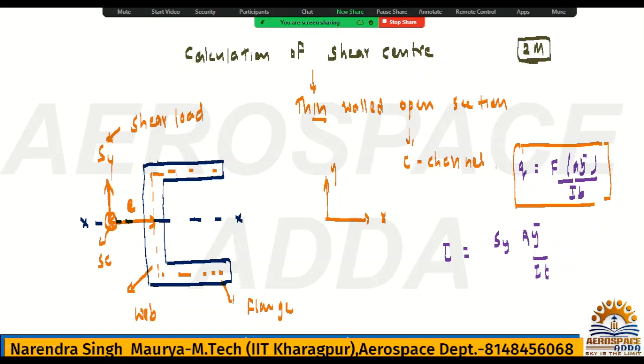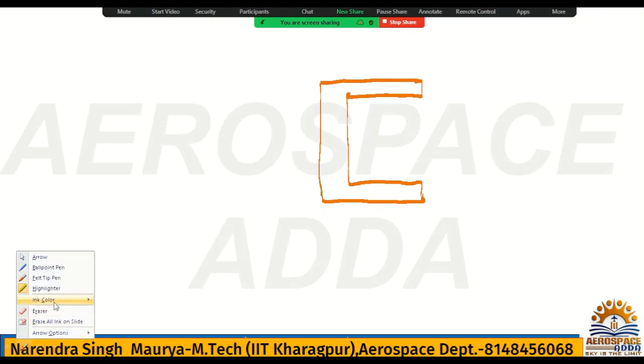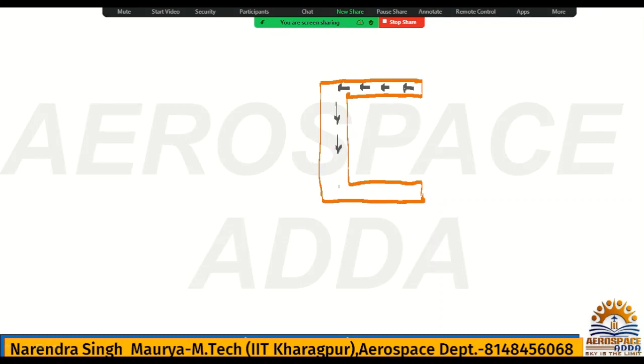If you take a C channel and draw the shear stress distribution, you may get it like this, and you should be aware of this. For the C channel, the shear stress distribution will be like this, and shear flow you may also get here. Suppose this is the C channel. If you check the shear stress distribution and shear flow, because of the shear force acting, shear flow you may get like this. This is called shear flow.